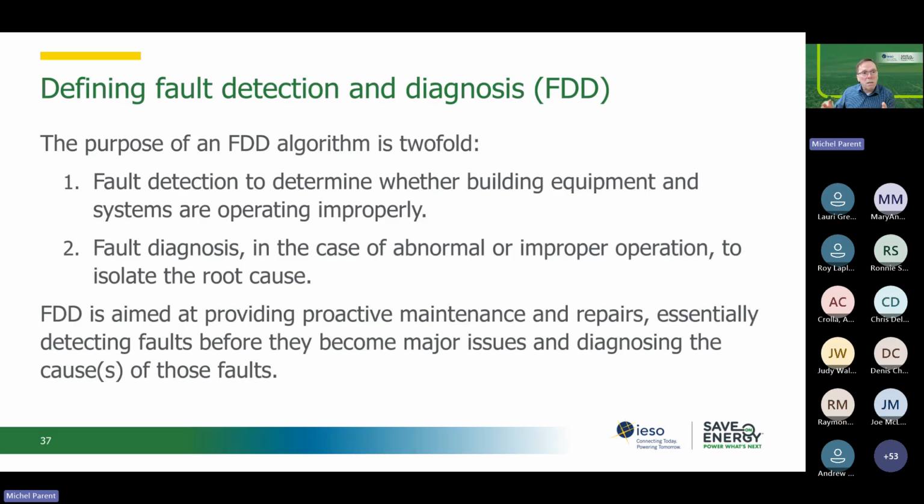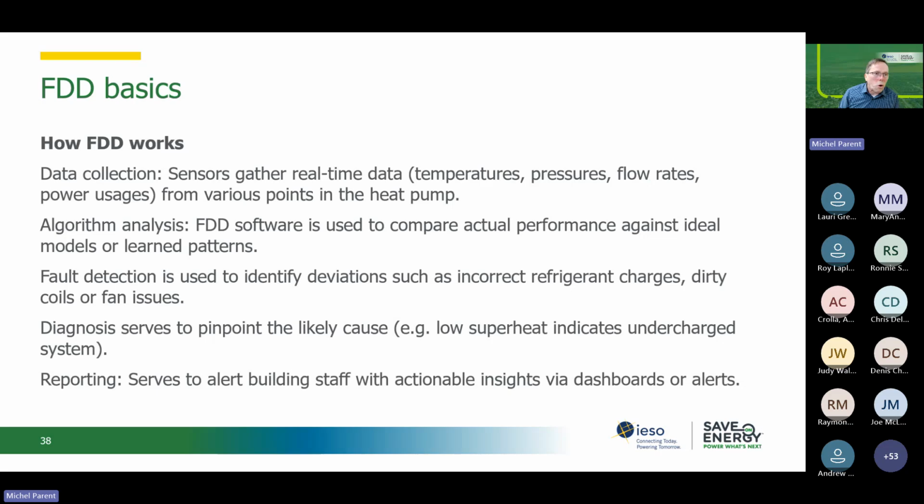So the FDD itself, as you know, has 2 real big portions. There's the fault detection, so they will gather all of the data. They have rules in there. Some of them have a little bit of AI, just a little bit, and they will spit out reports, which are the diagnostic. And in order to do anything with an FDD, you got to work on the diagnostics. So you get those diagnostic reports. If you do nothing with them, you might as well not have the FDD.